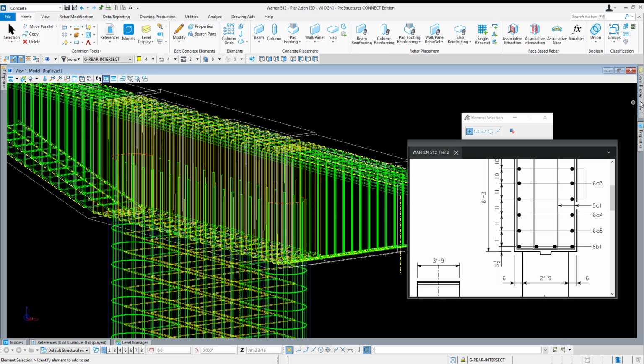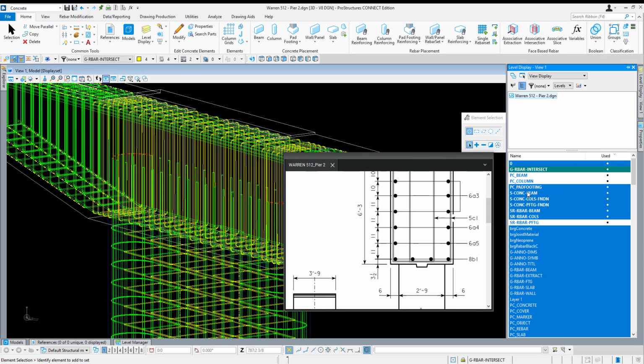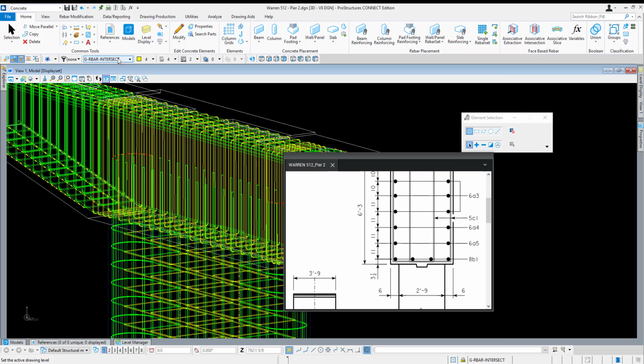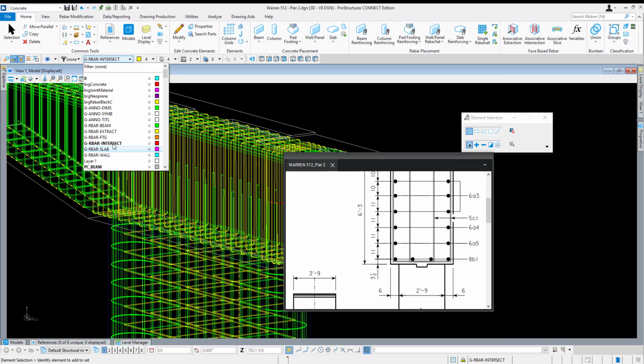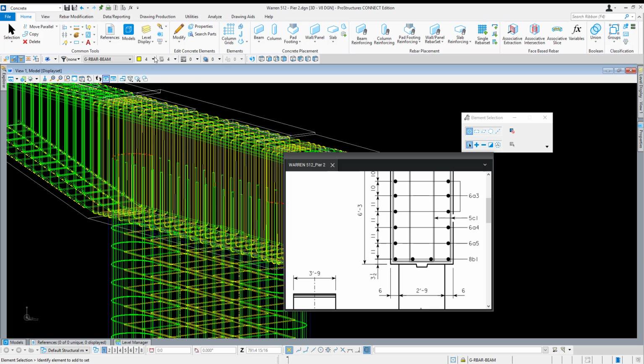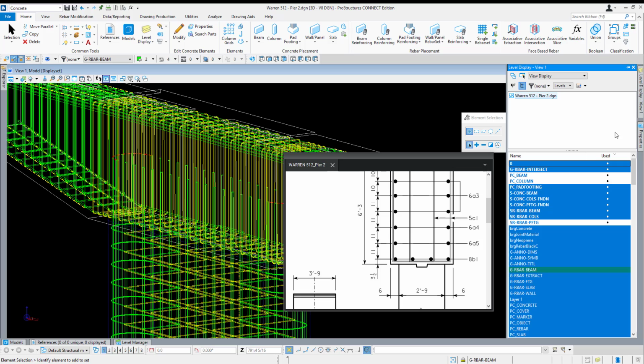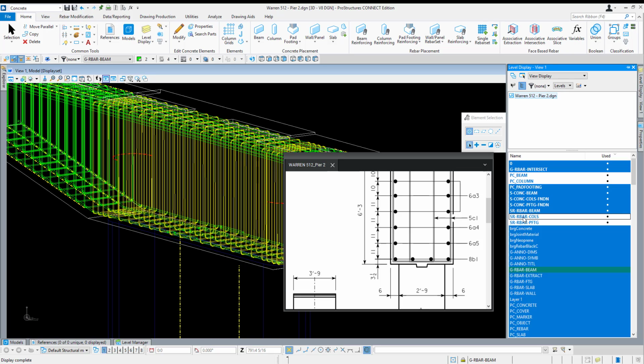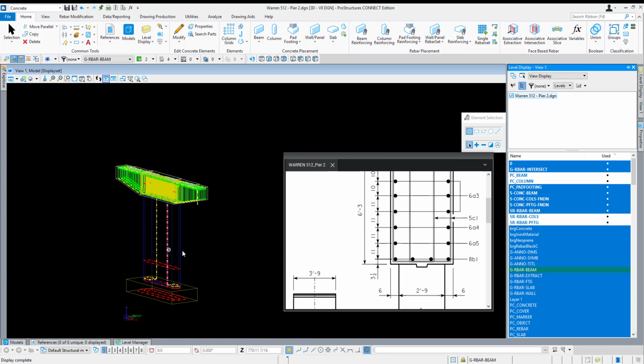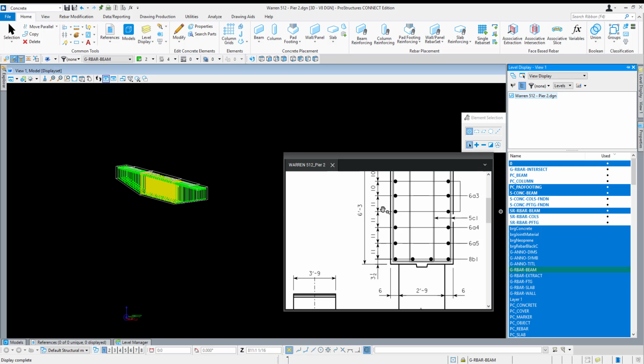So what I'm going to do is turn off all the levels that I don't need real quick. Getting a little busy in here. Actually going to shift to a different guideline level. There's one for beam, perfect. And let's go by level. And turn off our levels for the column reinforcement. And should be good there. Also don't need the column concrete really. And all of the other guidelines that I've placed. We do need our beam. Don't need the pad footing.